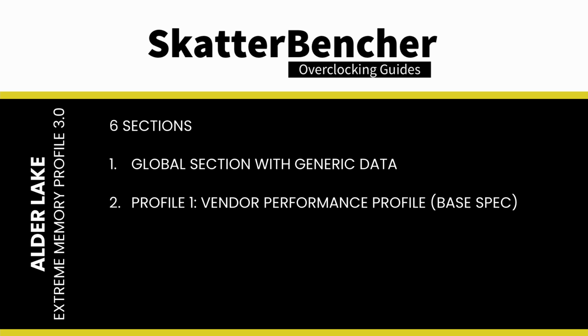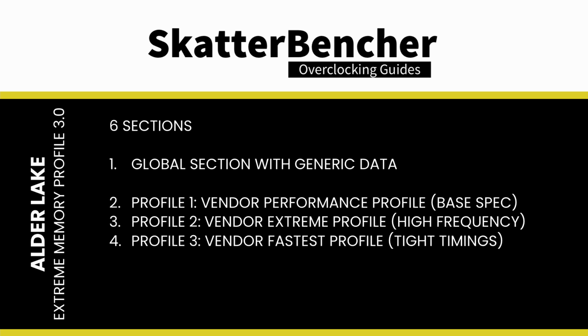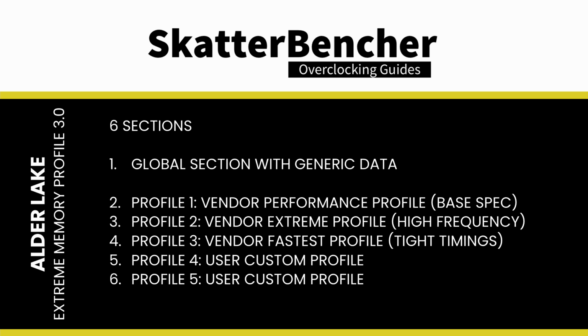Profile 1 is meant for the performance profile. This is the standard XMP as we know it. Profile 2 is designed for the extreme settings. This could be higher frequency at higher voltage. Profile 3 is designed for the fastest settings. This could be tighter timings at higher voltage. Profiles 4 and 5 are rewritable and meant for user custom settings.